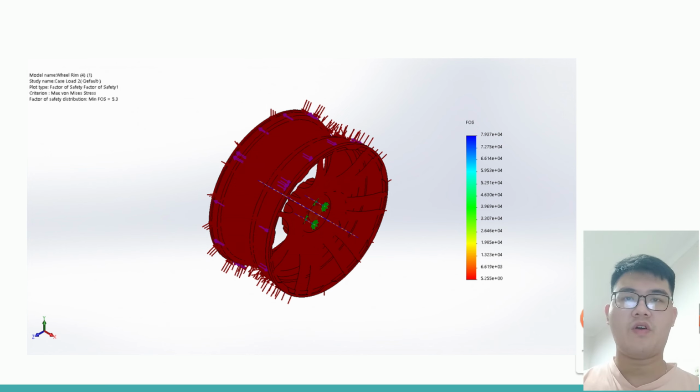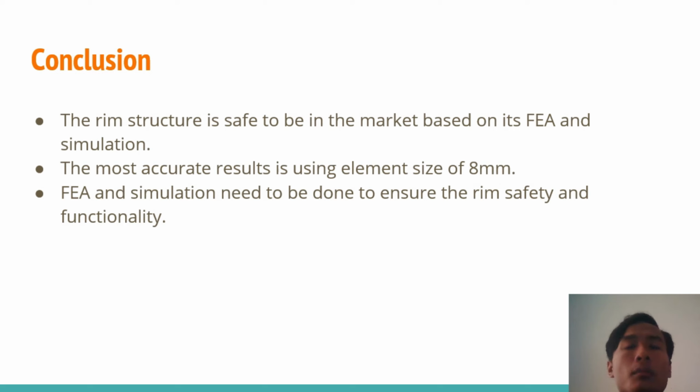For the conclusion of this project, based on the analysis and the simulation that has been done, the rim structure is considered safe to be in the market based on its finite element analysis. The most accurate result is obtained with an element size of 8 mm.